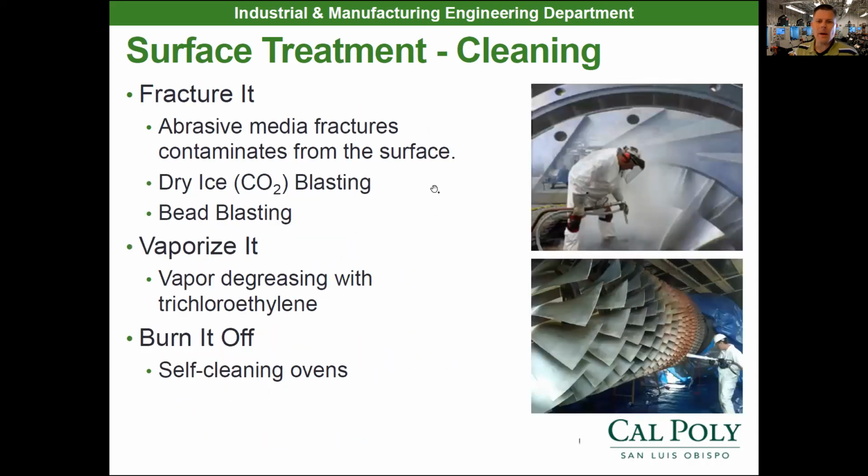Now, another way to do it would be to fracture it. There's something called media blasting, or bead blasting. They have dry ice blasting, if you're just using CO2, like to remove paint. They blast dry ice beads onto the part to remove paint. That abrasive media fractures the contaminants from the surface. So you're actually fracturing off a top layer when bead blasting and removing a small amount of material at the same time as cleaning it. That may or may not be advantageous for your process.